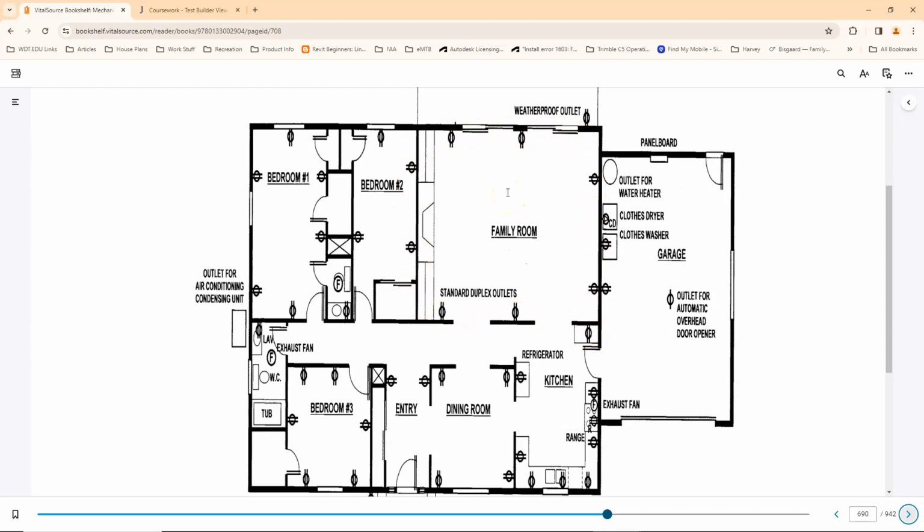In a kitchen, the maximum distance between outlets is 3 feet, and then any dedicated circuit to a piece of equipment that is higher voltage, like a clothes dryer, is going to have its own dedicated outlet. But that's kind of it. That's the main rules that we have to talk about in addition to the AFCI, GFCI stuff.